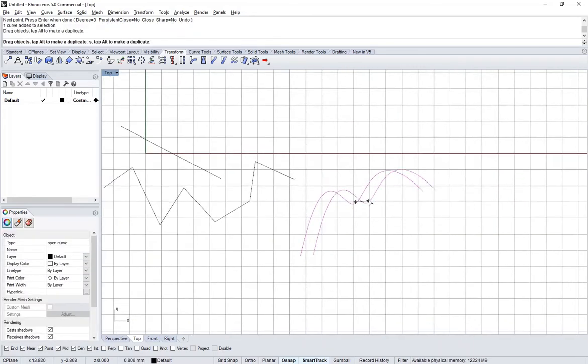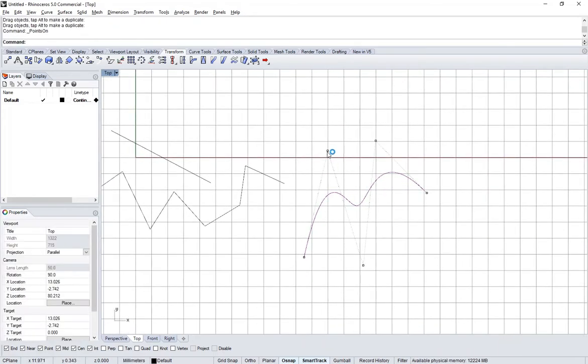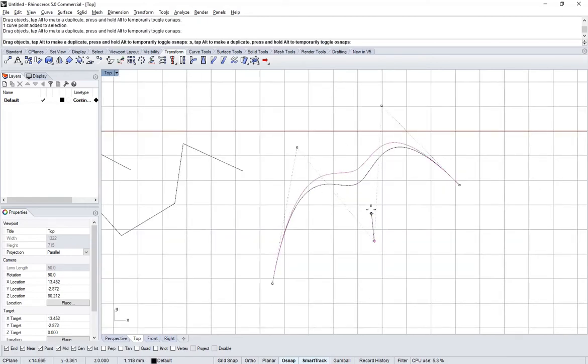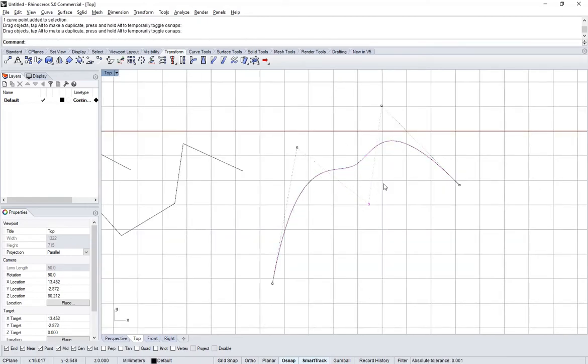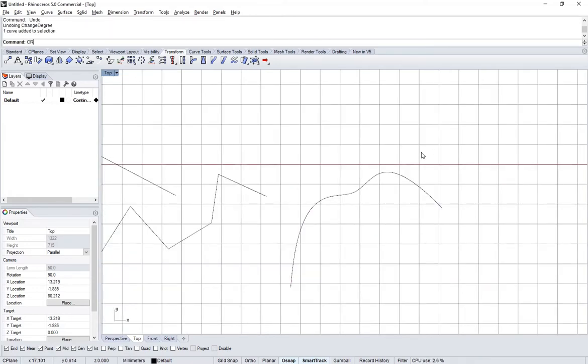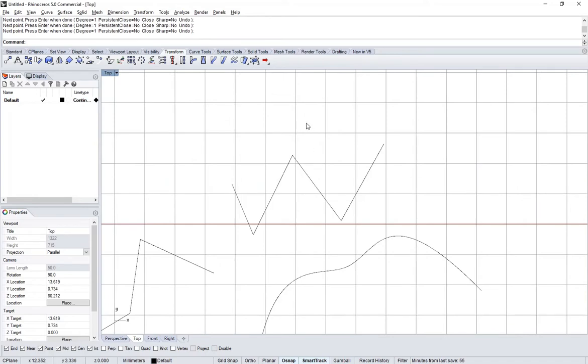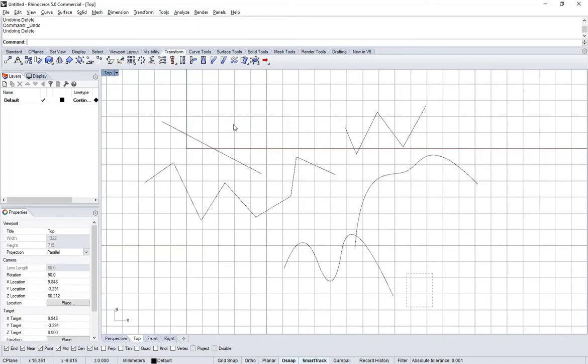Now here's our curve. We can hit F10 to reveal those control points we created. But you can see how the curve isn't actually going through any of the control points except for the first and second, because it's interpolating and smoothing out that control polygon. So if we use the curve command again and we change the degree to 1, we're actually going to be creating the polyline again. So let's do a quick experiment.